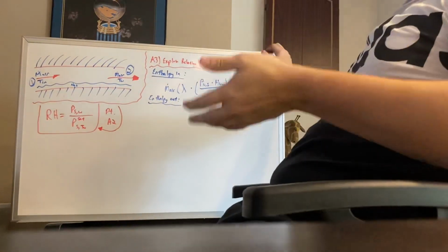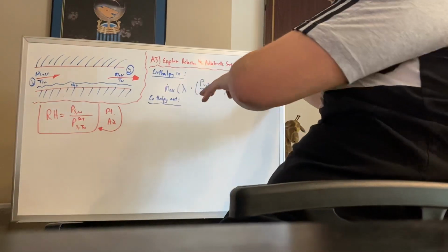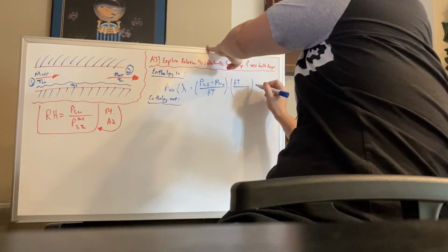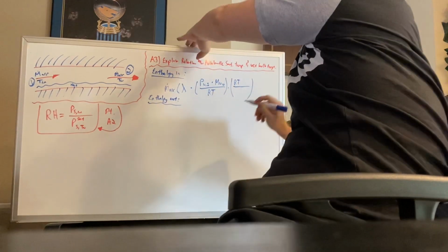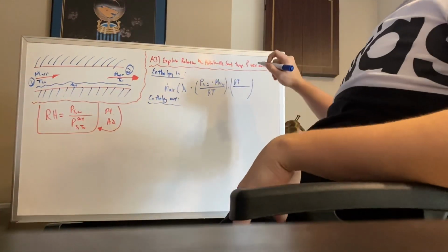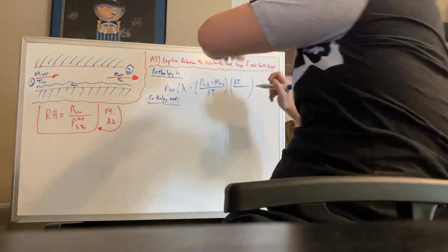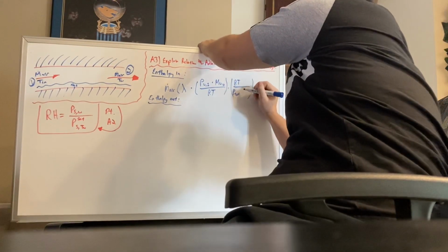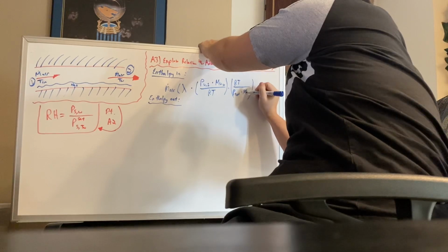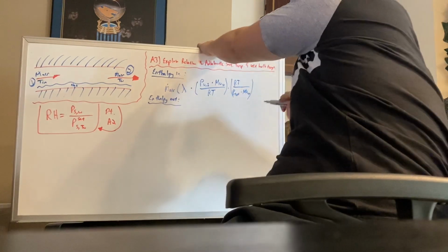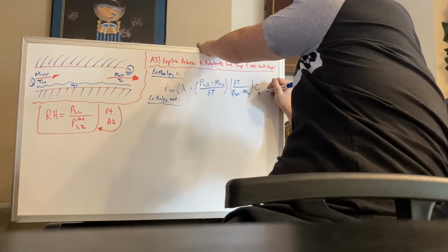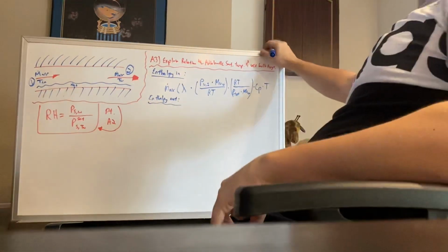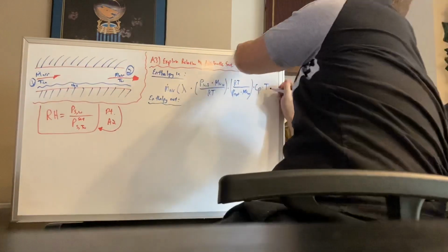The other part on the outside of these parentheses will be the gas constant multiplied by the temperature, divided by the total pressure multiplied by the average molecular weight. Then this is going to be multiplied by the heat capacity multiplied by the temperature of the inlet feed.